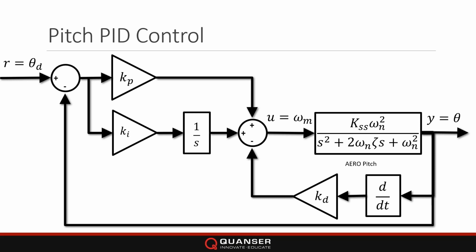So the PID control, again, is not quite your standard PID because we are feeding back the derivative directly, right? So this is basically a PI controller with rate feedback, is the proper terminology. And when we're simulating this in MATLAB and doing the design, we're assuming that there's no rotor dynamics, so effectively you have a perfect rotor speed control. That is how we're doing the control design simulation.